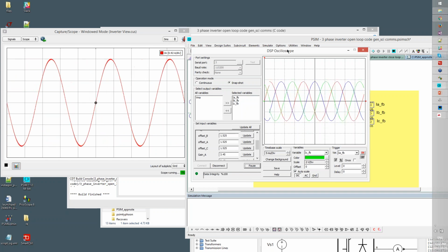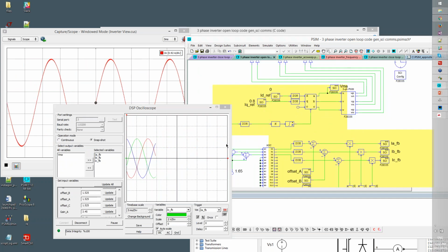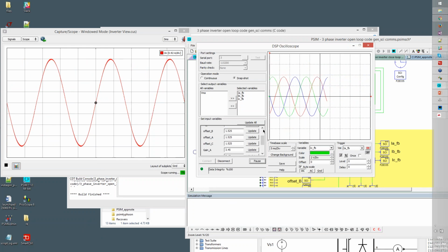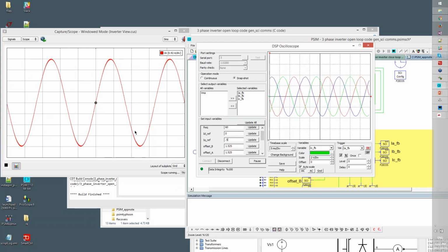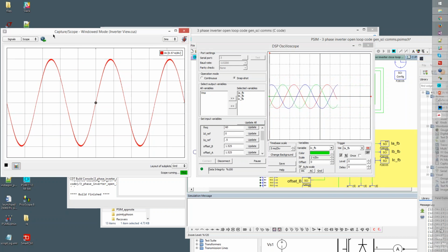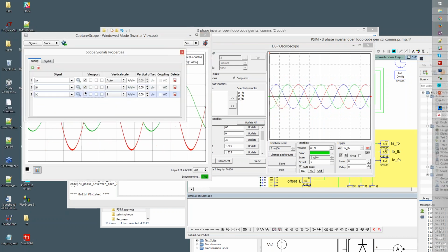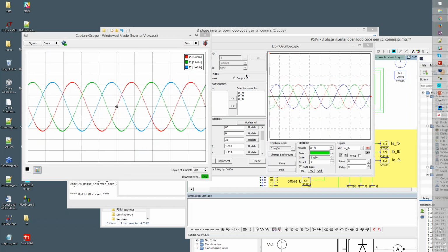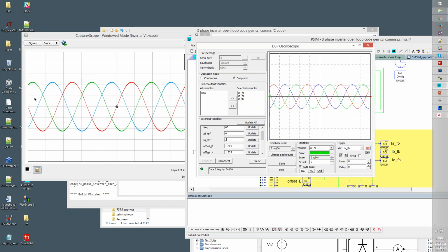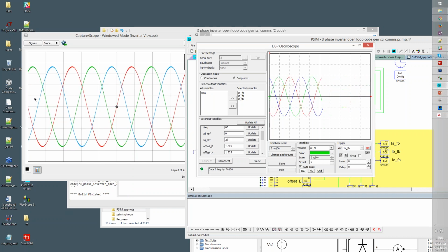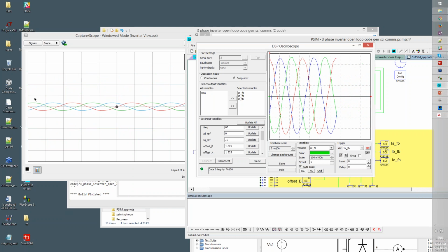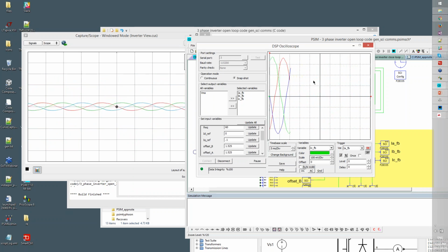Now the next thing that I've got set up here is we can double check to see what's going on a little bit. So I've got access to IQ and ID, so I can actually change in open loop the IQ reference. Let's make it smaller, and we can see everything. Oh, this auto scale is really quick. Let me just take this off, put these back on, and put this back on 1. Okay, so I'll play with IQ. So I'm changing IQ on the fly here, so we can change it back up to where it was, make it small again, 0.1. So we can change all these signals. The auto scale is making it maybe a little difficult to see what's happening.